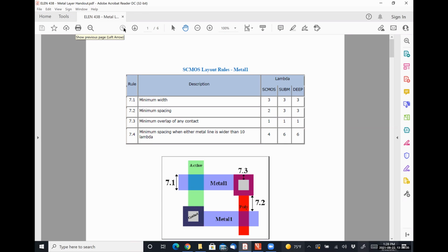we've got a general idea of the behaviors of N-well, metal, and other resistors. But I want to talk about voltage coefficients and temperature coefficients, because they can actually affect how the resistances and capacitances that we design behave. Because all of these things are based on semiconductor materials whose properties are extraordinarily temperature dependent.